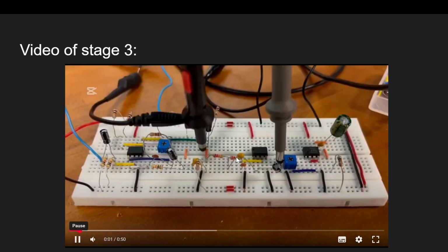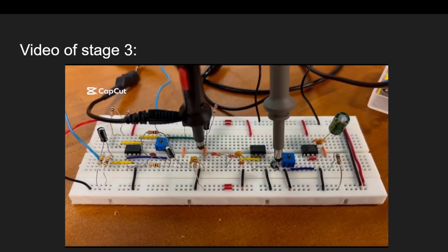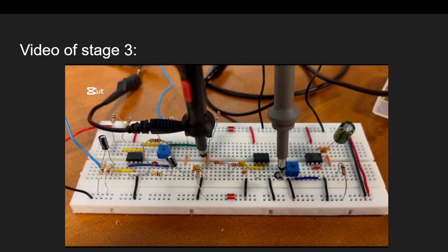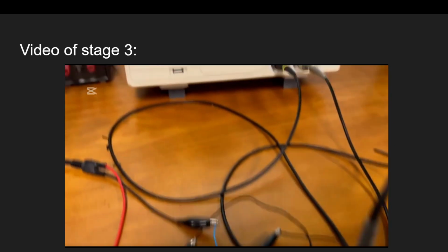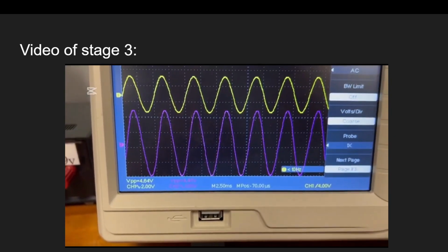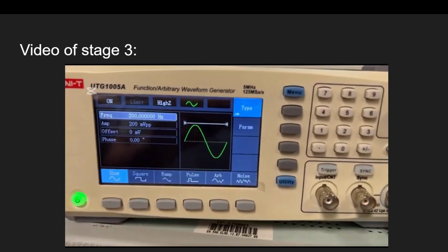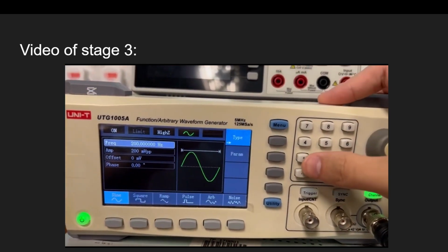Now this is my video recordings for stage 3. To record for stage 3, we will leave test probe 1 at TP3 and connect test probe 2 to TP4. The output voltage is then measured at about 4.4 volts. This occurs when the function generator is set to 200 Hz and 200 mV peak to peak.